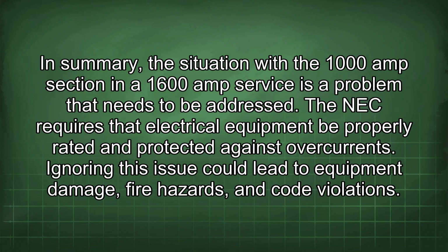In summary, the situation with the 1000 amp section in a 1600 amp service is a problem that needs to be addressed. The NEC requires that electrical equipment be properly rated and protected against overcurrents. Ignoring this issue could lead to equipment damage, fire hazards, and code violations.